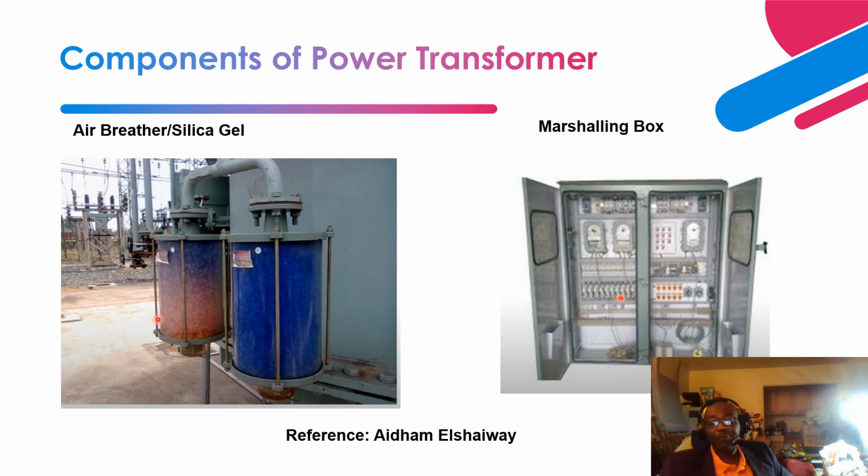The goal of the heaters is to keep the condensation away, because when you have condensation on the terminal blocks, it is going to cause a short and can cause a spurious tripping of the power transformer.